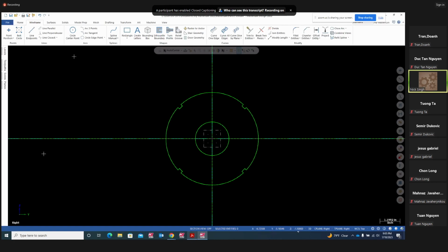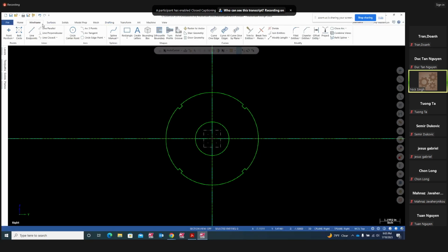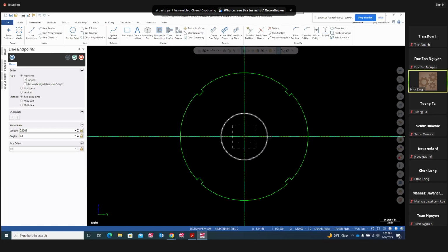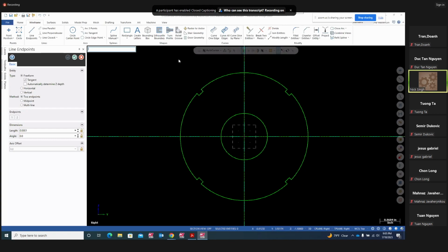Now here we're going to draw that line 35° and 35°, those two lines from that point right there. So create a line from that point. Oh my goodness, we can type that point right here. Start point is going to be x is going to be 1 inches, comma 0. That's where my arc starts, and I'm going to go this way right here.